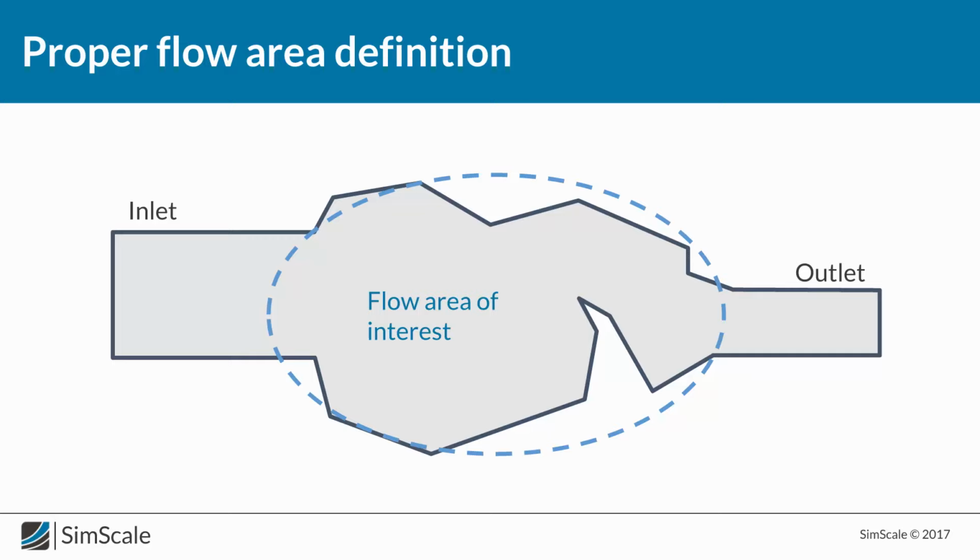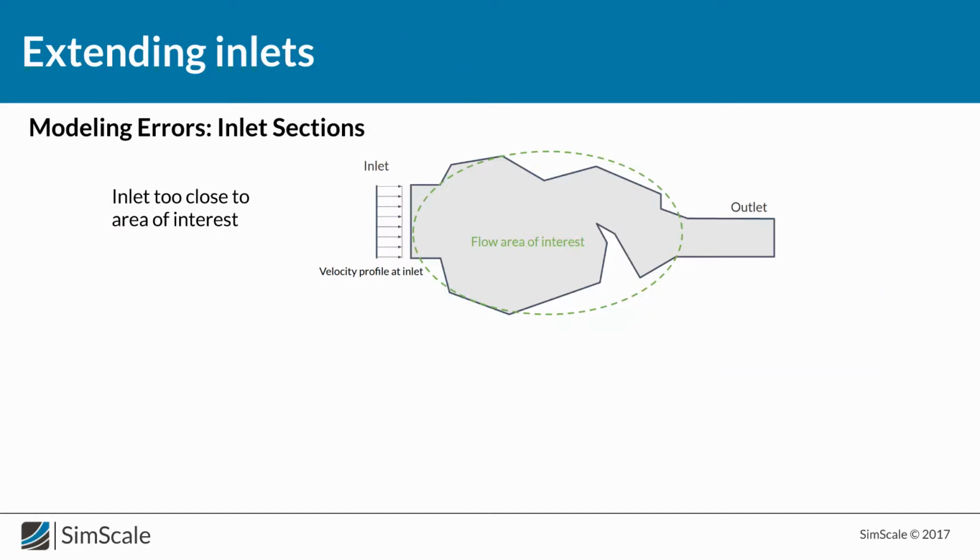Unfortunately, it brings together with it some dangers for the stability of the system itself while it is being simulated. Why is that? Well, let's take a look first at the inlet sections, where we are introducing the flow into the domain. Most of the time, the inlets will be presented with a single uniform velocity, meaning that everywhere at the face, which is an inlet, the velocity will be exactly the same.